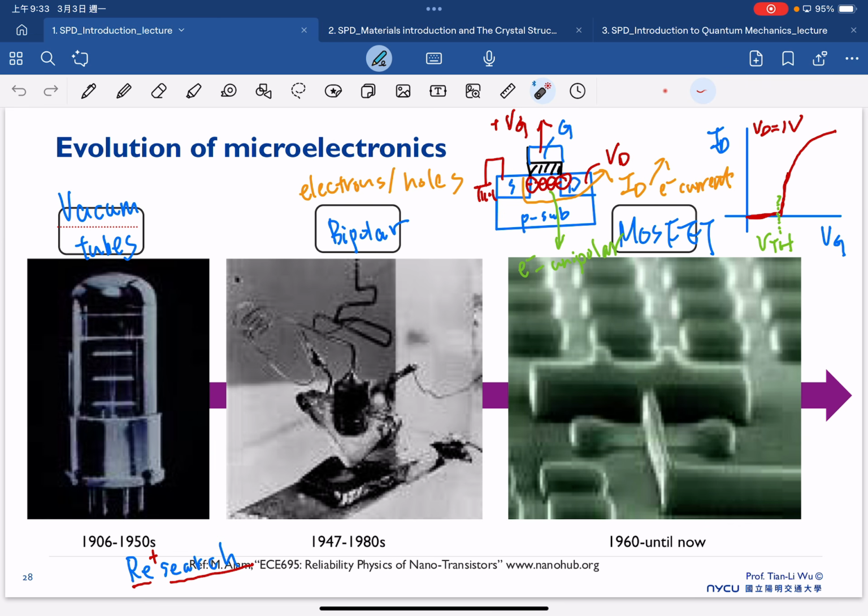So the typical operation for the MOSFET is, once we apply enough gate bias, for sure we will start to attract electrons under the channel. This doesn't really need very complicated physics. It's just pretty simple high school physics. Once you apply a positive gate bias on one side, for sure you will start to attract electrons, right? The negative electrons will try to flow to the positive gate bias.